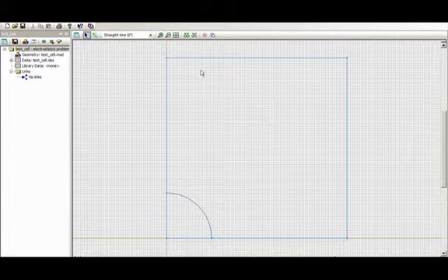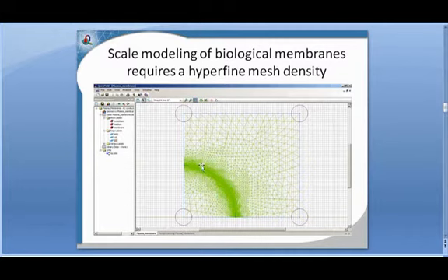And I'm not going to mesh this one here, and we'll look at a different example. I just want to show you how to set this up. And if we're looking at an electrostatic calculation, I would apply a boundary condition, constant voltage here, and I would apply constant voltage here on this region. And I don't need to apply any boundary condition along the z-axis here, nor do I need to apply any boundary condition along the outer boundary of the cell. Okay. So once I mesh this, it'll have an image like this, and it'll take a few minutes to solve. So we'll go ahead and solve some smaller problems in interest of time.